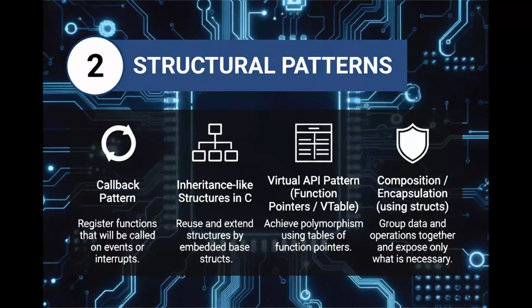This slide talks about structural patterns. The callback pattern is the first structural pattern that we're going to discuss. The callback pattern is essential in asynchronous embedded systems. Instead of polling continuously, modules register callback functions.